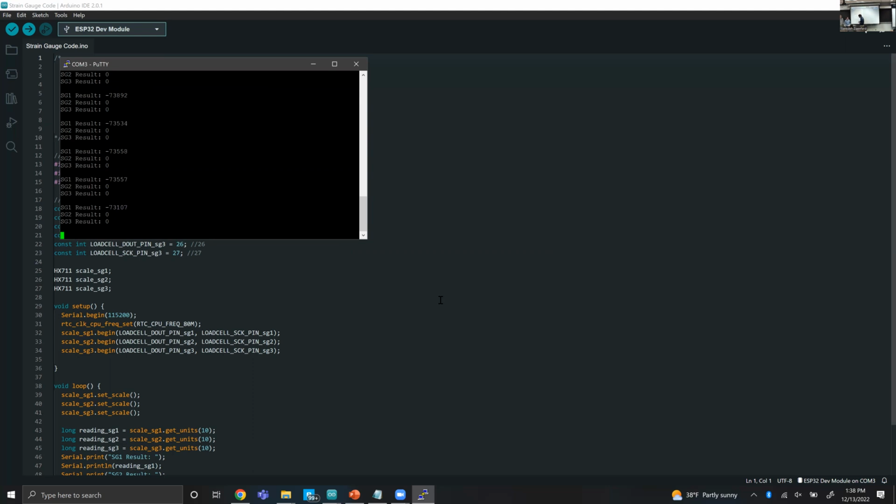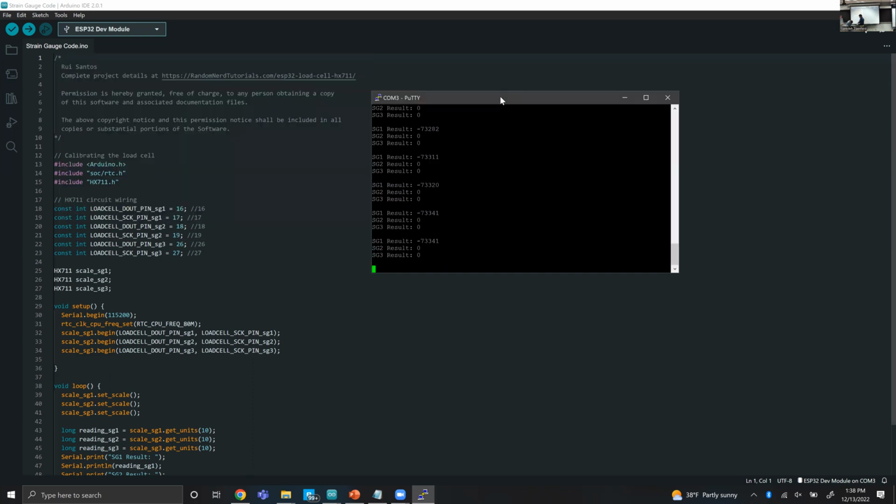That's because I haven't been able to design and build a calibration stand yet, so I haven't been able to calibrate it. Tell me how you want to calibrate it. There's code already that you can calibrate with, through the libraries that this HX711 amplifier board has. You can calibrate the load cell.